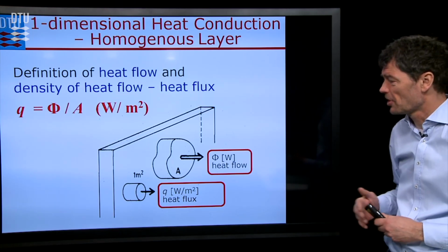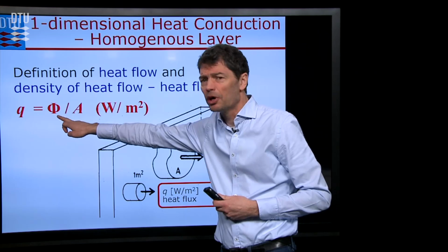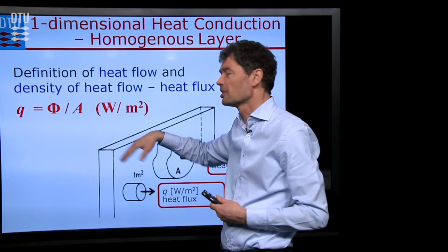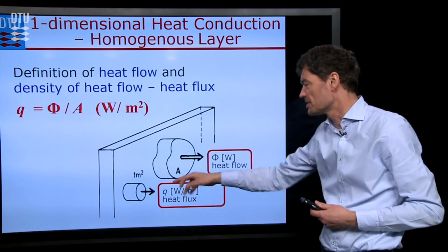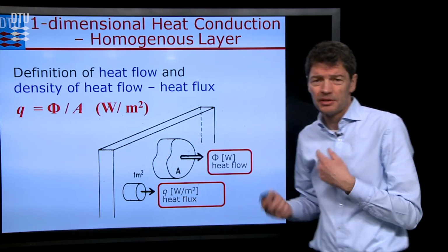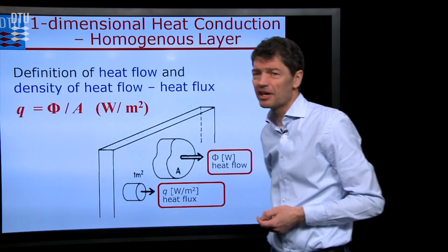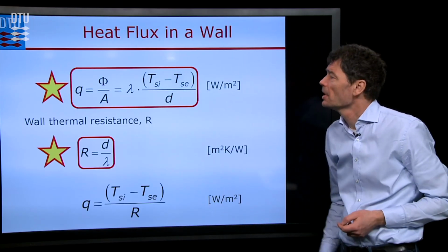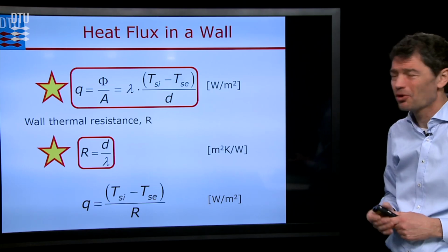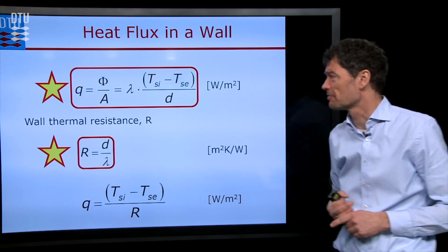So also, we talked so far about the heat flow in the unit of watt, but very often we talk about heat flux. Flux is the same value but only taken per area, so it's a specific value of the same. So flux q is equal to the phi value divided by the area A. Then, again, Fourier's law is written in this form, where we now write it in terms of flux.